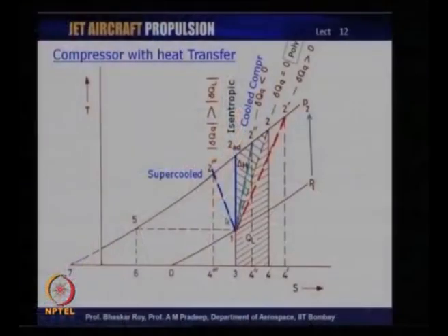There is a process here which shows that if you do a lot of cooling, which one can call supercooling, you can get away with doing a lot less work to accomplish the same pressurization from 1 to 2 triple prime. So, the pressurization would indeed be achieved, but it is possible that you would arrive at a temperature of a lower value at the end of the compression process, even lower than the ideal.